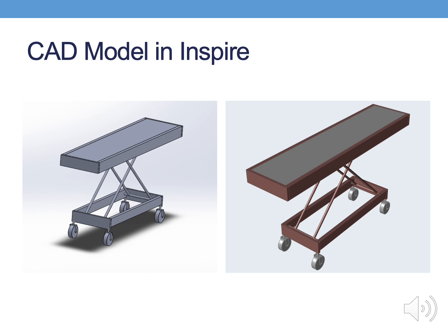In order to find the optimum design for the stretcher, I created a simple SOLIDWORKS model of a stretcher that fits the constraints laid out in the previous slide. Then I imported this model into the software Inspire. This is shown on the right. The maroon color indicates the design space, and the gray is the non-design space where loads and supports will be added. This is important because Inspire will not run an optimization where there is a load or a support added in the design space. In addition, Inspire allows you to assign material to your design.